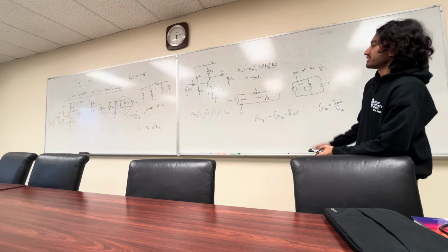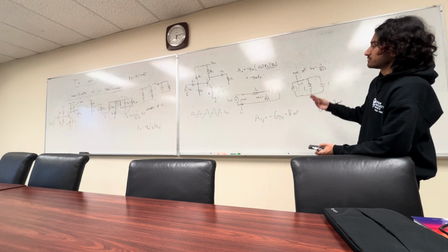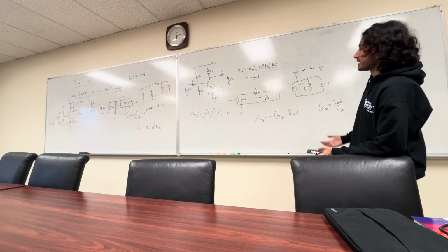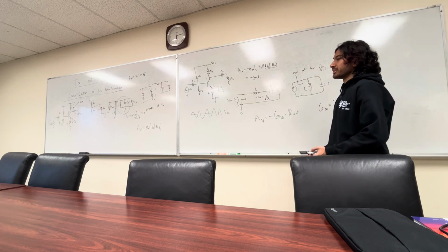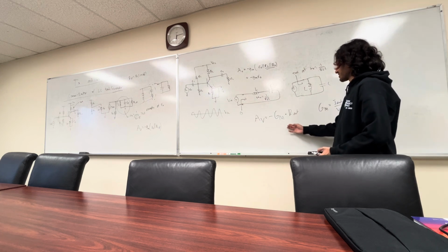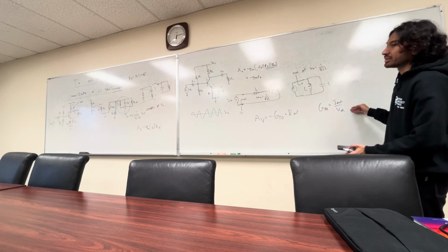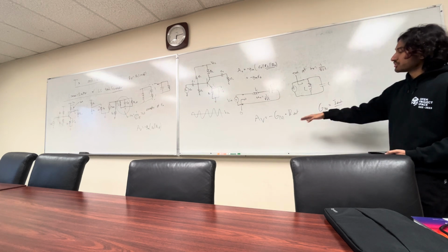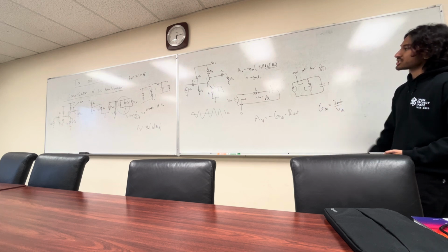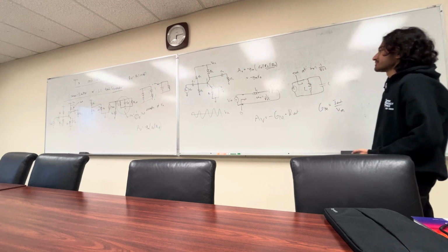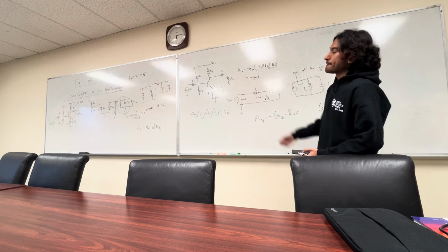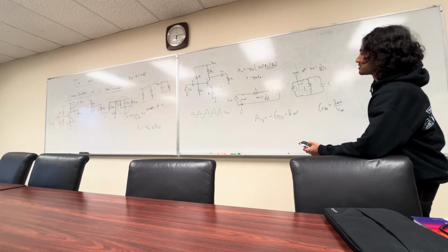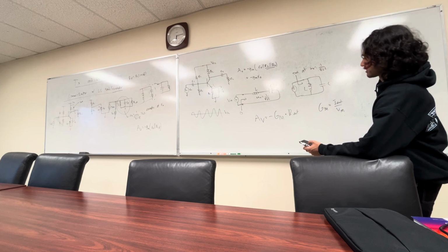But effectively, the fact that we have no voltage drop from supply to collector means we, in a way, get more current, and GM is basically how much current we get for a certain input voltage. So we get more current, GM is a bit larger, so we end up with both increasing, and gain goes higher. At the end of the day, we can never beat this limit. That's always there. But we can try to get as close to it as possible, and that's the goal.